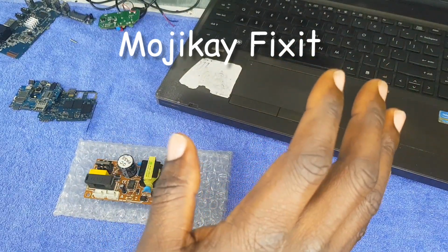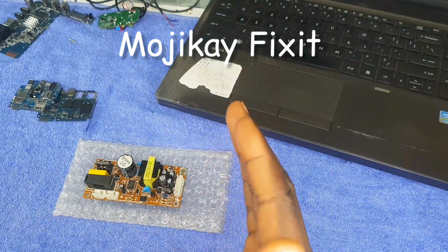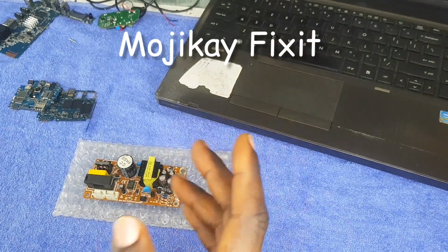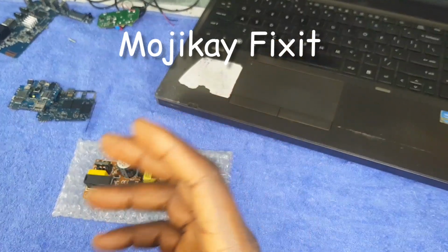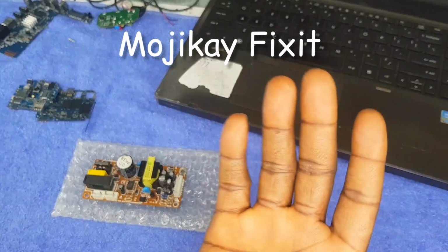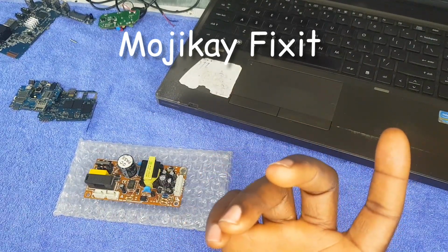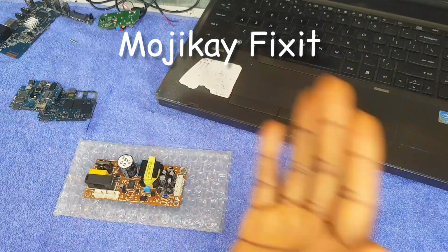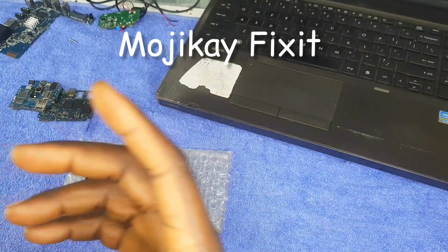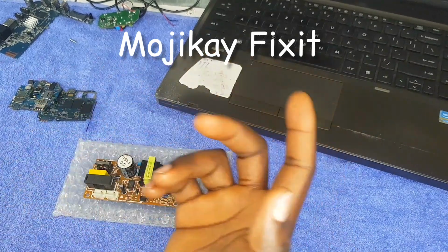So what is the importance of these resistors? Number one, they limit electric current from flowing. Also, they divide voltages. You can use a resistor to divide voltage; I'm going to show you shortly. We can also use a resistor to generate heat. We have a lot of uses for resistors. We can also use them to gain control, to set time constants, and many more like that.